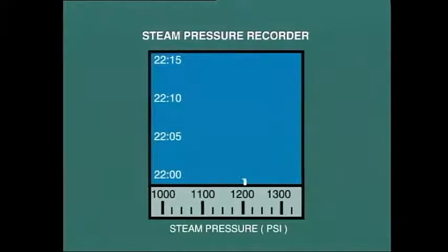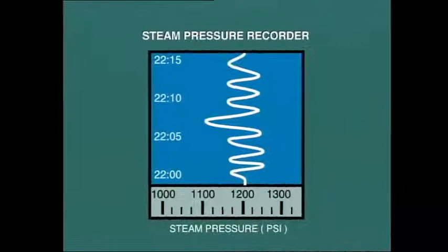One disadvantage of this simple system is that it must wait for the pressure to actually fall before commencing a corrective action. And even then, some more delay is experienced in mechanically changing the airflow and fuel supply. Yet further delay is encountered before the increased combustion brings about the desired rise in pressure. The cumulative delay from this control system results in a fluctuating steam pressure. This situation can be vastly improved by adding a second element to the control system.